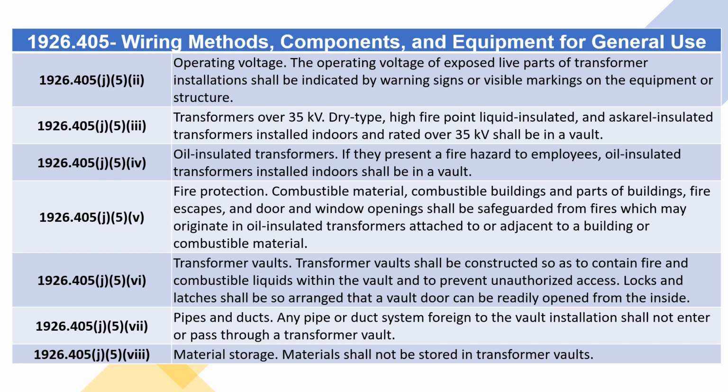Transformers over 35 kV. Dry-type, high-fire-point liquid insulated, and Askarel insulated transformers installed indoors and rated over 35 kV shall be in a vault. Oil-insulated transformers. If they present a fire hazard to employees, oil-insulated transformers installed indoors shall be in a vault.